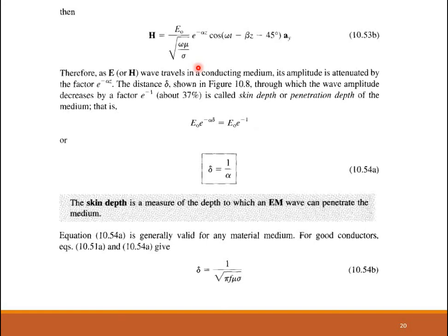And for good conductors, the angle is exactly 45 degrees. Correspondingly, the expressions for E and H were also obtained. So till here you should know. Whenever you are asked to describe the propagation of plane waves in any medium, you derive the general vector Helmholtz equation and then derive these constants. That is how you proceed.